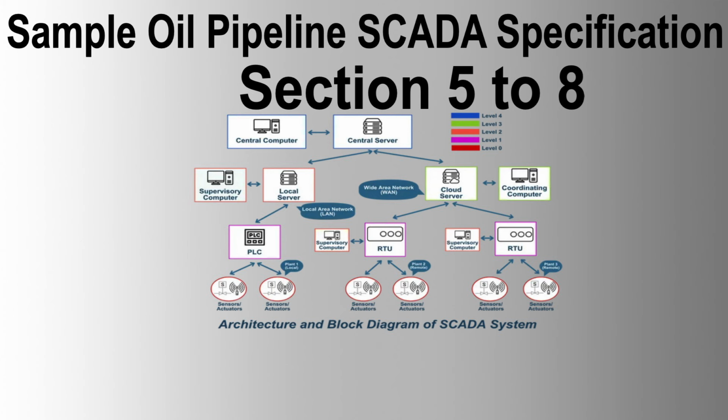7.8.2 Historical database. Real-time data saved into a disk-based historical database system using RAID disk array. Transfer of archived data to CD-ROMs via a CD-ROM burner. Database engine based on industry-standard products such as Oracle and Sybase. Proprietary database systems are not permitted.